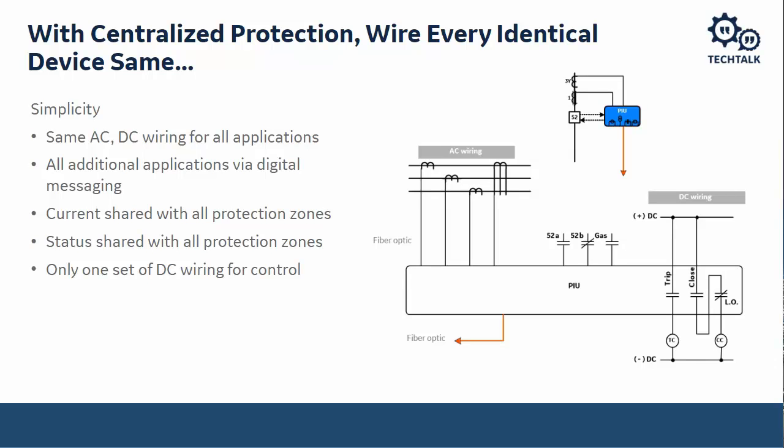I've done some stuff where you needed to add in something like recloser cutoff status to an adjacent breaker. That was not a big thing. You got to add in some wire from a contact output of one relay into an input of the other. Simple enough, except that the construction crew had left. And so we're trying to scramble to find wire to wire this in. If we had something like this where the information was available over a network, then with a matter of programming, you could have that signal in there and been done and added that in.